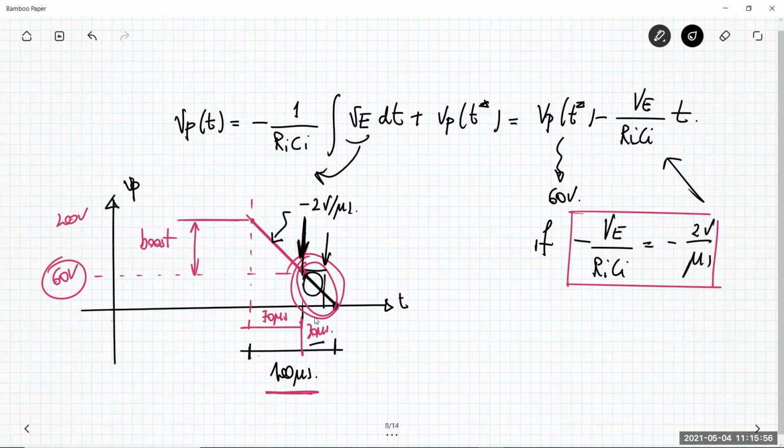And so the energy that I have to dissipate is not possible to dissipate. So I need a transistor that can be closed fast enough to cover all the 30 microsecond interval. As a matter of fact, I can choose a MOSFET having a turn-on time interval which is a small fraction of 30 microseconds.